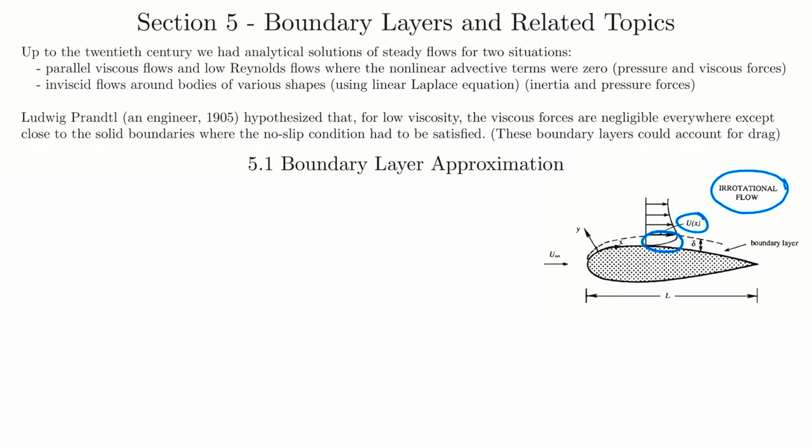Now, a note on this figure: the boundary layer thickness is greatly exaggerated in this picture just so we can see it and visualize it and I can talk about it. It's not this big at all. For example, around a typical full size airplane wing, it would be roughly a centimeter thick, right? So it's actually quite thin.